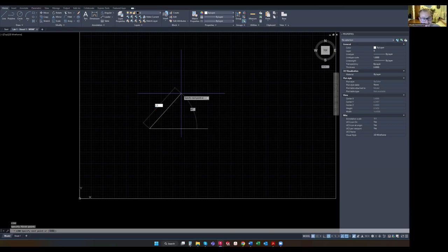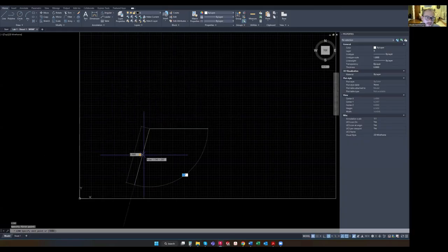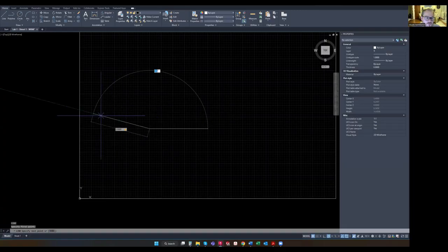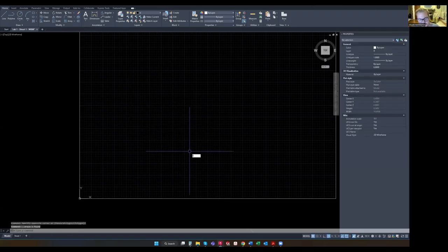2.5 tab, you can see that then I'm entering the angle. So that is what we're looking at there. And you can also see here the angle only goes to 180 degrees above and below the line. So that's something to keep in mind. If I'm going to redraw our initial line at 5.5, 3, so we're going to start that there.